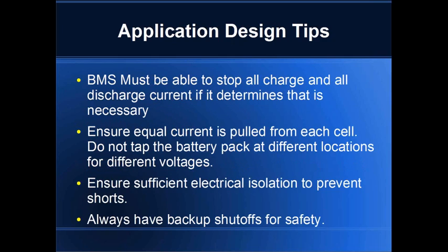So here are just some design tips that we've run across. First of all, the battery management system must be able to stop all charging and all discharge from the battery if it determines that it's necessary. Like I said earlier, you can have a battery management system that monitors the battery pack perfectly, but if it doesn't have a way of shutting off the charge and discharge, it doesn't do you a whole lot of good.